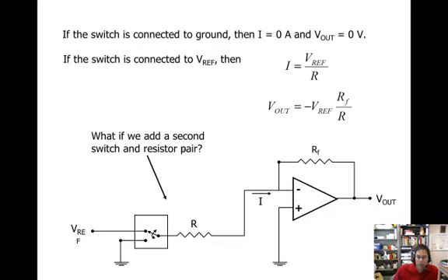So how do we create an analog voltage? Well, we can start off by using an op-amp here, and if you remember your op-amps, basically no current's going into this input of this op-amp, and because of that, this amplifier here is going to have this voltage, kind of a voltage sharing thing. Remember, the current here is backwards, so there's a negative there. So we're going to have VREF divided by R, and it's going to be minus that. And so here, this could be the voltage reference, and this is our output here.